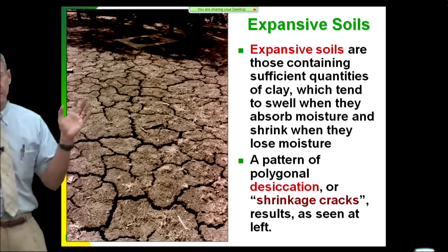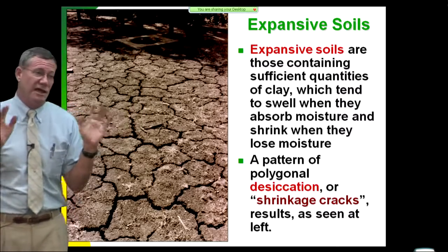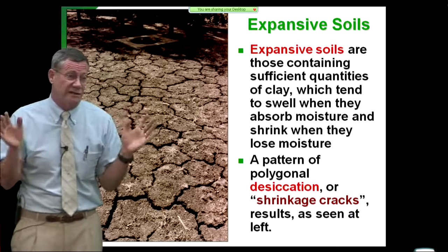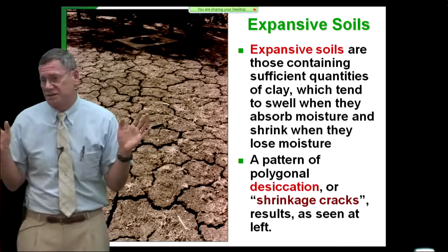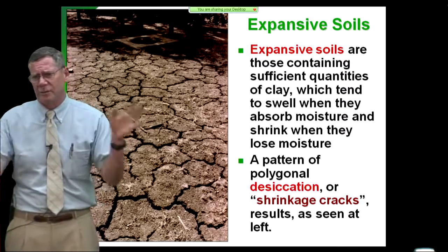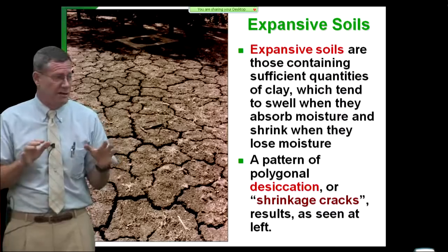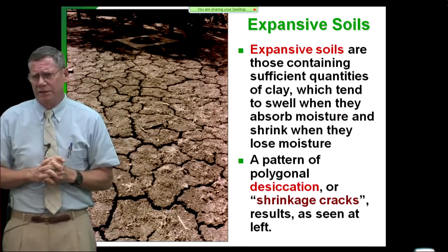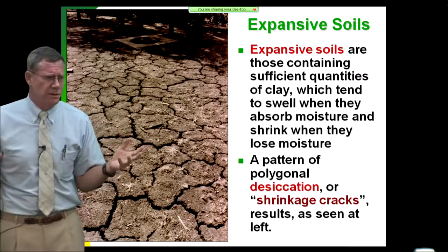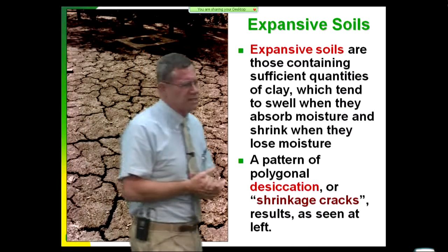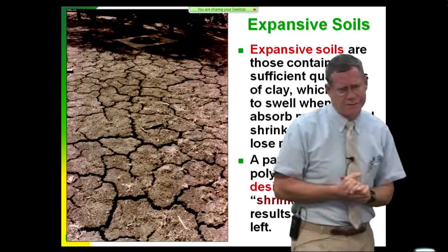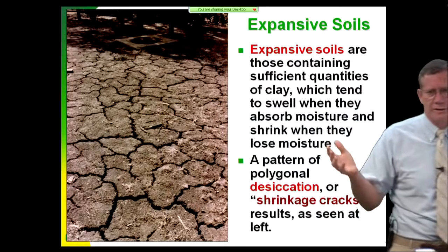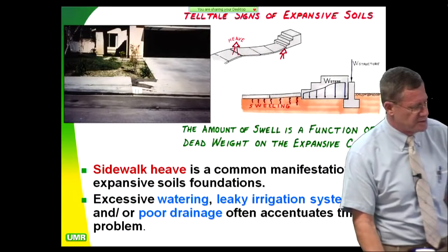Smectites are the really bad news. It's like catching HIV. If you get smectites in there, give the job to somebody else. Run, go practice somewhere else. Smectites can swell up to 300 to 800% of their dry unit weight. They're generally altered tuffs, specifically in the United States, mostly of Cretaceous age, the Bearpaw, Pierre, all those that are so famous.